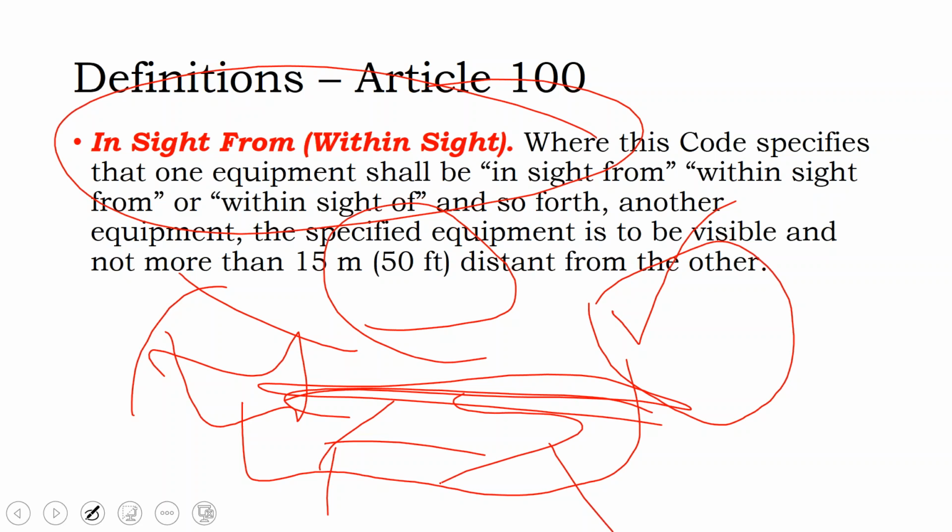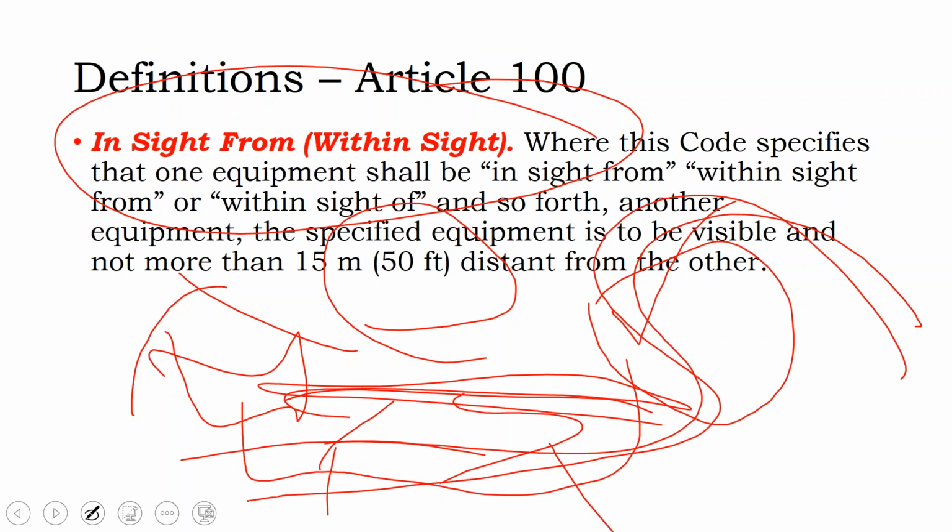Well, we thought we were being smart by saying, okay, so we don't need a disconnect switch. And so we're going to just take the 3 circuits from the solar array ground mount and run them directly into the ground, a direct burial run. So all we have to do is rent a trencher, dig the trench, throw the wires into the trench, and cover it back up. We were trying to get the most bang for our buck and spend money on solar and not on unnecessary equipment.